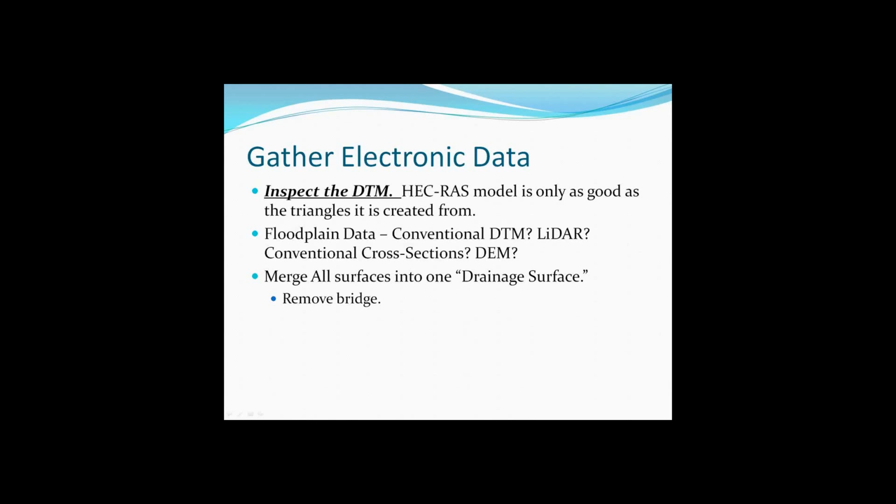Now LiDAR, we have statewide LiDAR, and we have that available for about half the state right now, and in the next few years we hope to have the whole state covered. And that's very cheap data because we've already paid to collect it. And it's also very good data for hydraulic analysis for the floodplain. It's not good for the channel, and we'll look at that in a couple of minutes, but it's very good data for the floodplain. So if that's available in your project area, you can go ahead and use that.